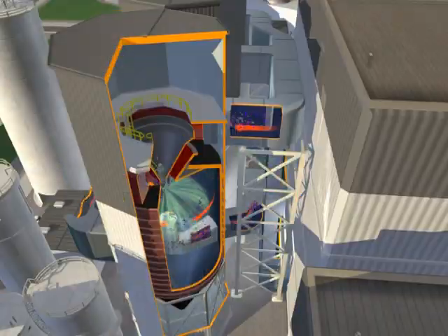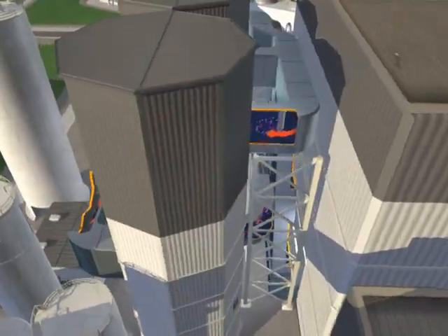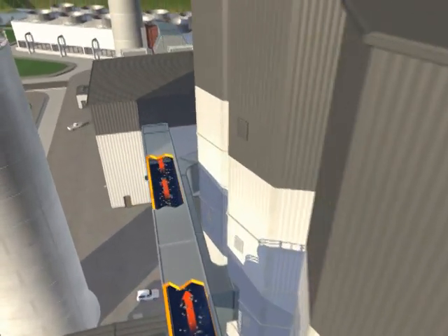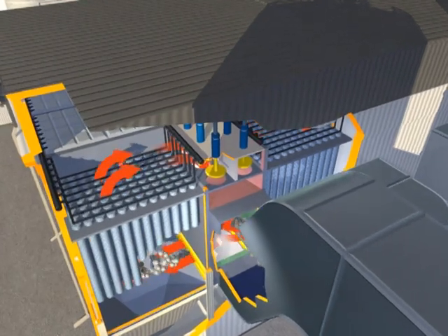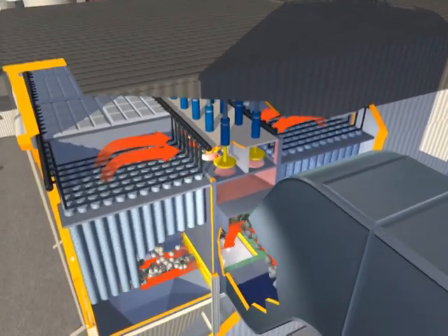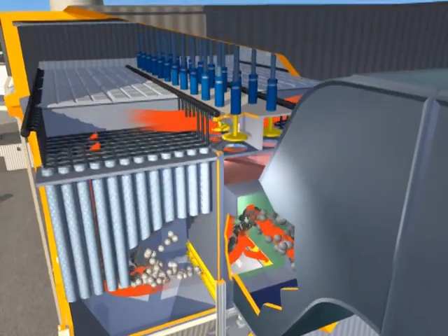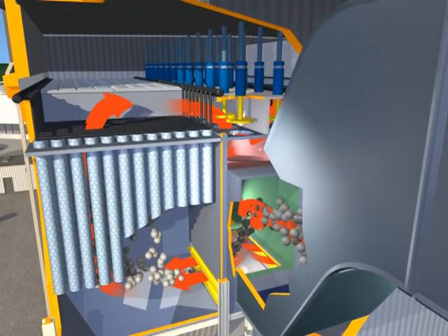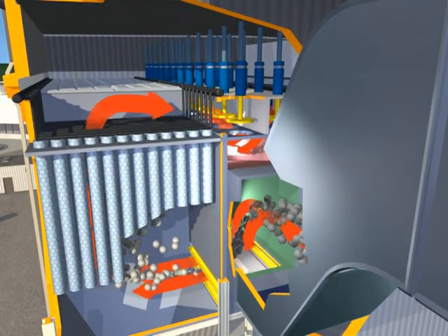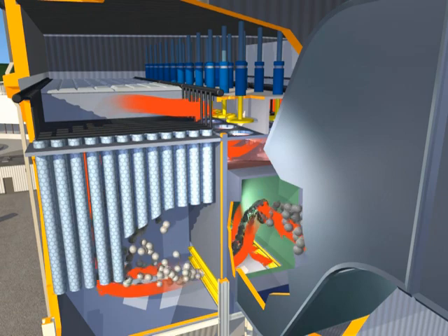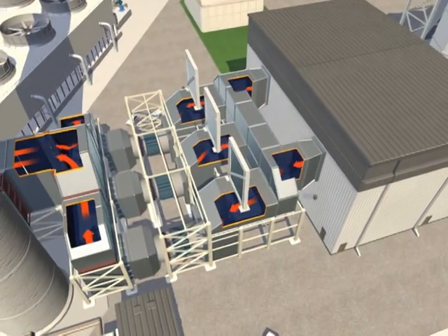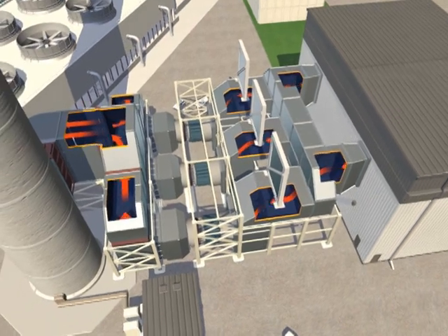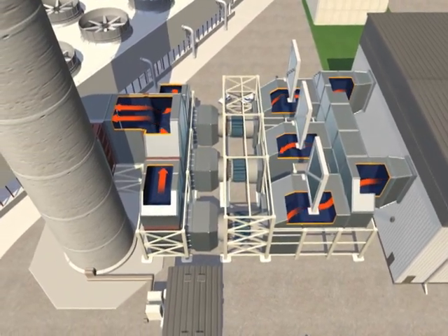The remaining particles are collected in the baghouse, an area containing large fabric filters. The baghouse acts like a giant vacuum cleaner to remove carbon, SDA dry product, and ash from the exhaust gases. The dry product collected here and in the SDA periodically is removed and taken to a landfill. After the gases pass through the baghouse, they are dispersed into the atmosphere through a tall stack.